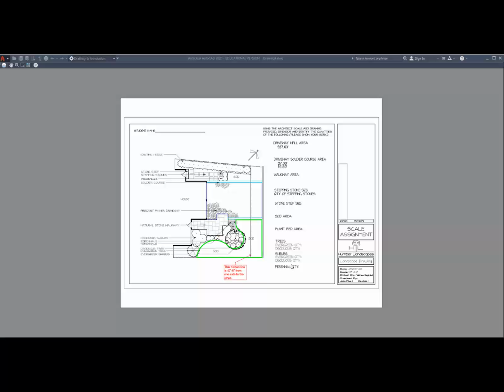Once again, we're using this because a PDF was supplied instead of a CAD drawing. If somebody actually supplies a CAD drawing, then we can use this technique without having to scale up a PDF. We simply go into the CAD drawing and create all the different layers and make our polyline selection based on the drawing or the line work that's already there. I hope you enjoyed this. Make sure that you understand it fully. It will be an exercise that we repeat throughout the program, so it's important that you understand the basics of it.